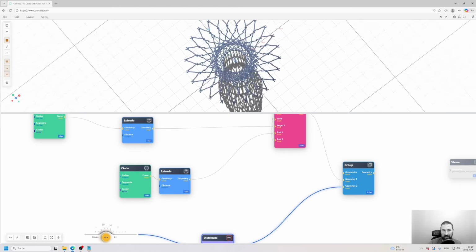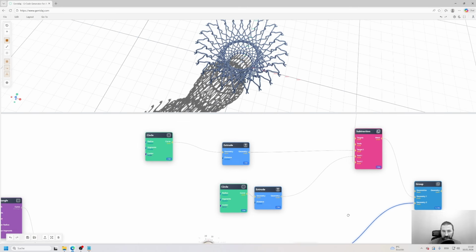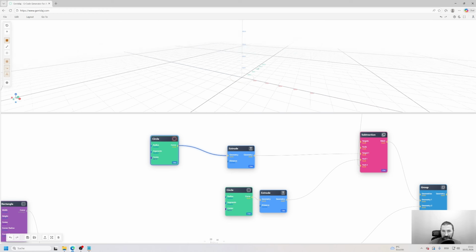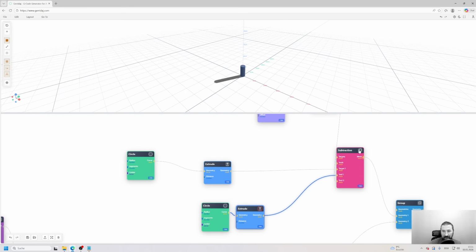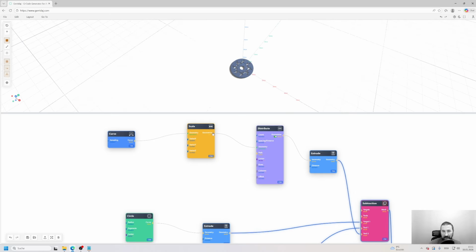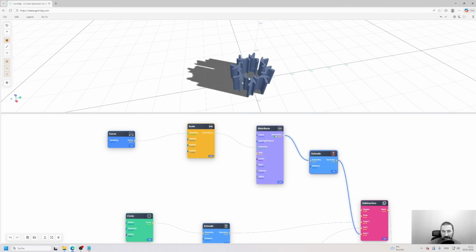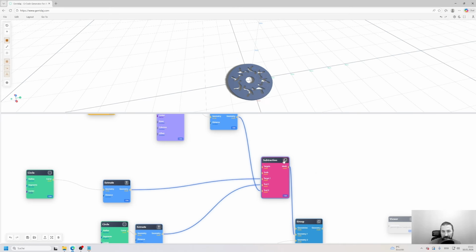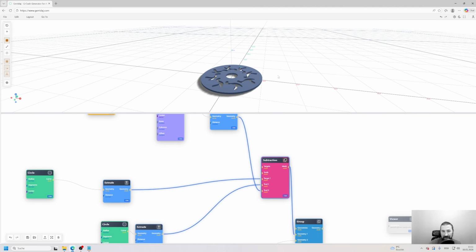And okay, you see in the example, we also had some base, and the base is in this top area. You see it starts with a circle. It's extruded. And we have a circle again. It's subtracted, so it creates a hole. But we have also some more subtraction here. And we subtract these shapes to create this kind of strangely shaped pattern of holes here. And this creates the base of our lamp.